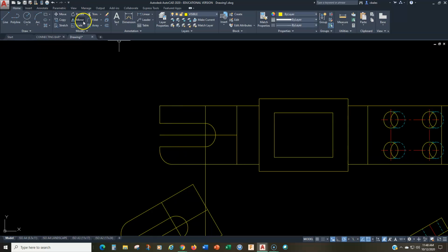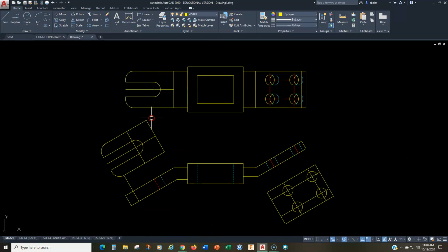Well, the same thing, just a mirror image. So let me show you the mirror command. I'm not sure I've showed you the mirror command yet. I think we kind of used it on some of our practice work. But mirror, select the object, right? So I want to mirror that, hit enter. First point of the mirror line, well, it's the line bisecting the whole object. So right there to there. And then I don't want to remove the original. And there we go. Okay. All right, so that's that. Oops, let me put that back in there. Let me trim it right there.